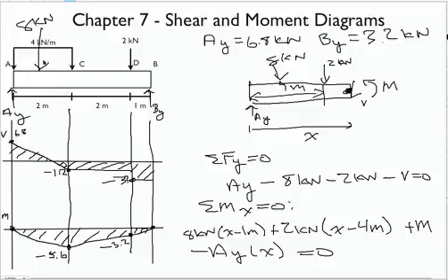Every single time the load changes, you draw another free body diagram that represents some sort of intermediate position that you label as distance X, just like you would on a graph. And then whenever you hit the end of this, you draw a new one, and then there's a change and you draw another one. Another thing that you can look at is what I like to call shear pushing. Each one of these forces pushes this shear curve around proportional to the amount of force, right?